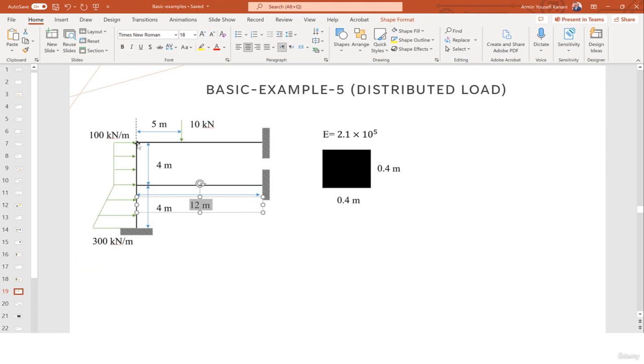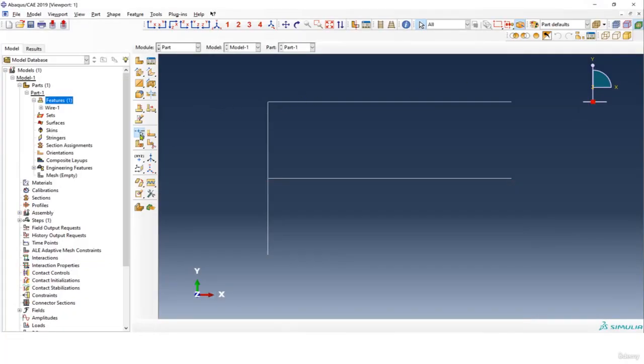So when we want to create a partition, as you can see, this is 5 meters from this corner, and we can actually do that very simply by going here and using a partition edge interparameter. And I can select this line and click on OK. But as you can see, the value is normalized. So basically you have to put a value from 0 to 1. So it's kind of like a percentage thing. And this direction is important as well.